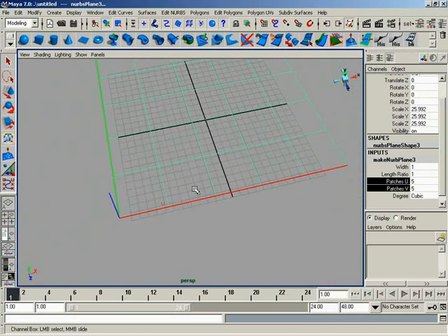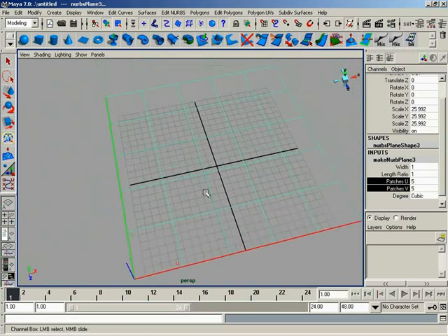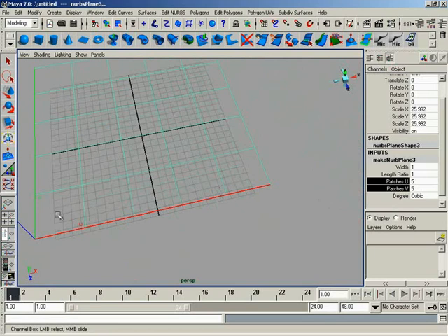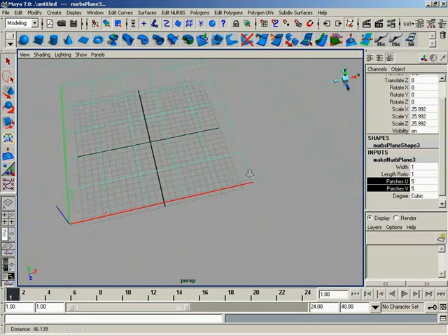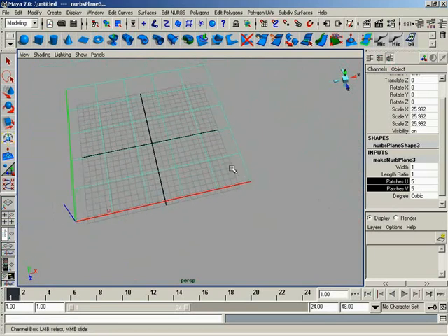If you are ever having problems attaching a NURBS surface to another NURBS surface, always check your surface origins first and make sure that you are trying to connect V to another V and a U to another U, and it's the end of one surface to the beginning of another surface. Make sure that everything lines up before you try your attachment.